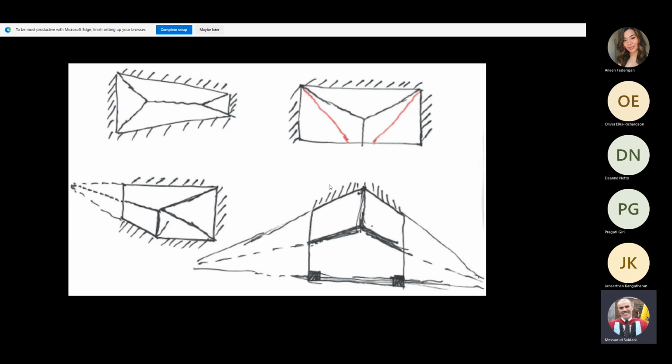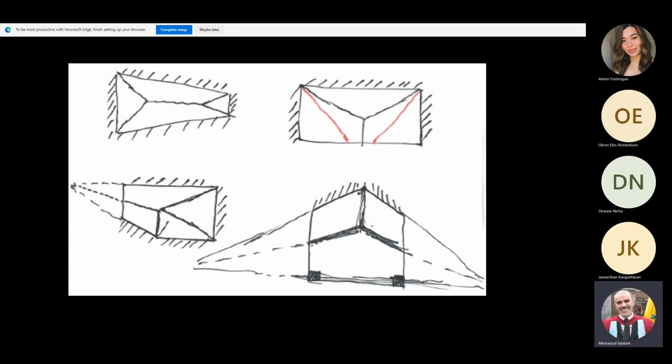Okay, so it's very easy. You just need to follow the rules. And there are two key rules that you need to remember. Number one, the yield line starts at the points of maximum curvature. And the yield line will then extend to the point of intersection of the axes of rotation, like we have here. Any questions? Is that okay? Anything at all?